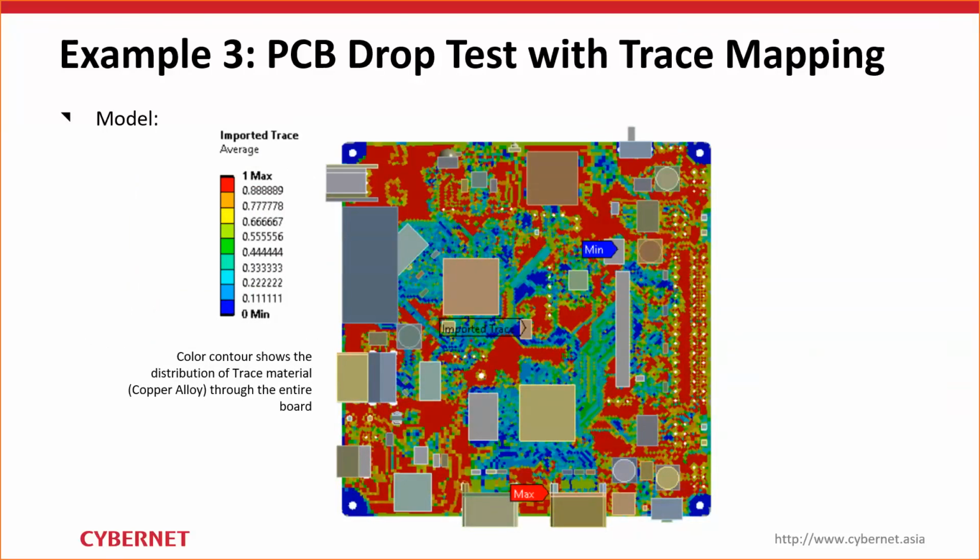So the finer your mesh is, the higher the fidelity or higher the accuracy of the trace is going to be. In this particular case, I say that the accuracy is okay. You can definitely opt for a higher level of fine mesh, but for this particular case, I say that it is quite satisfying.